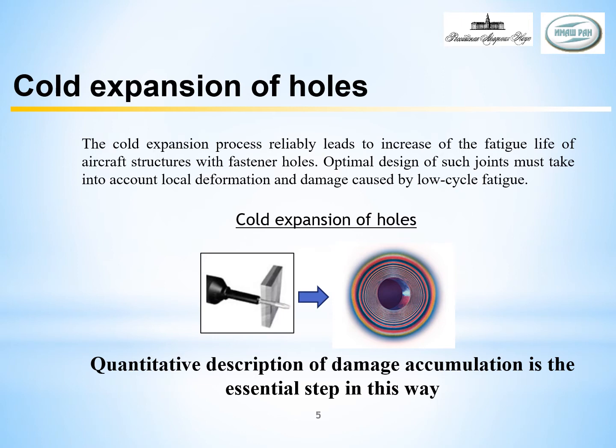The cold expansion process reliably leads to an increase of fatigue life of aircraft structures with fastener holes. Optimal design of side joints must take into account local deformation and damage caused by low cycle fatigue. So, quantitative description of damage accumulation is the essential step in this way.